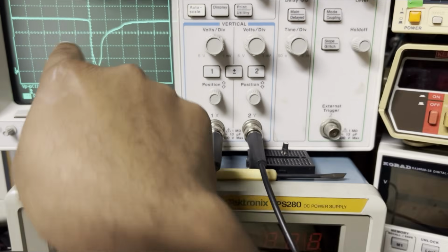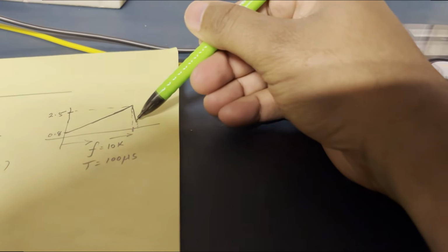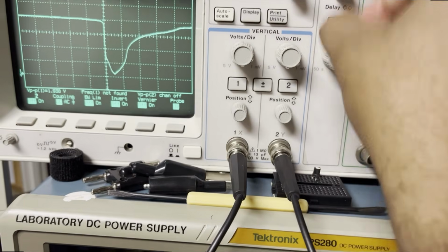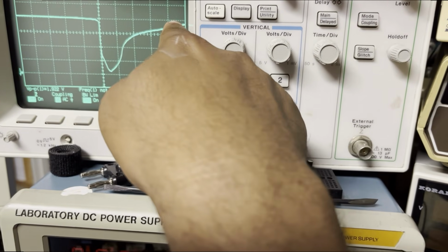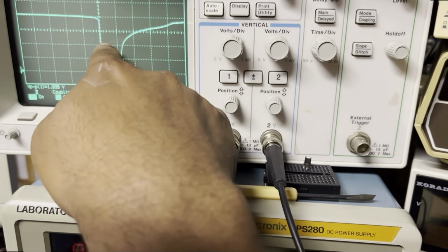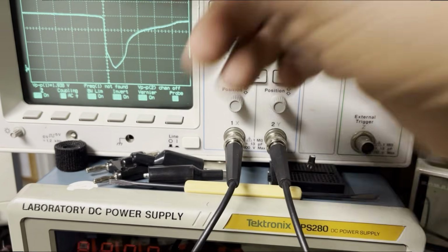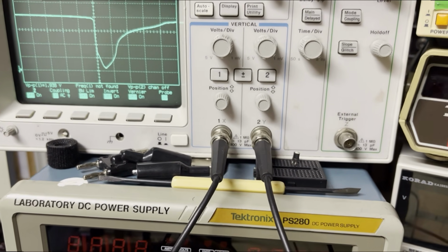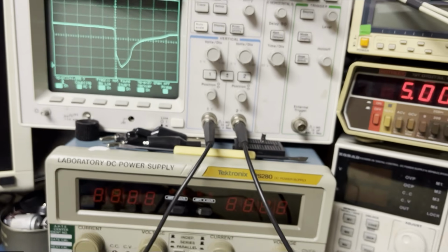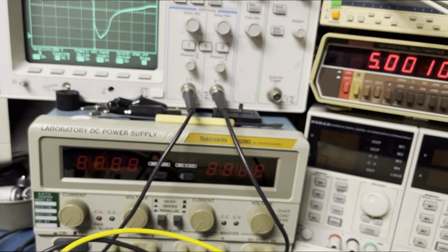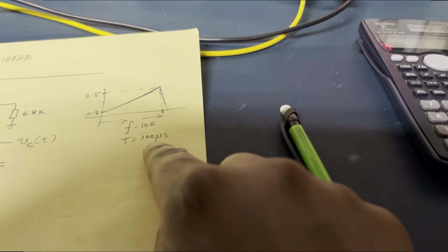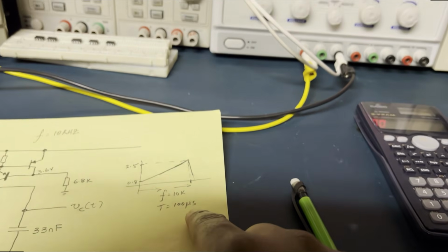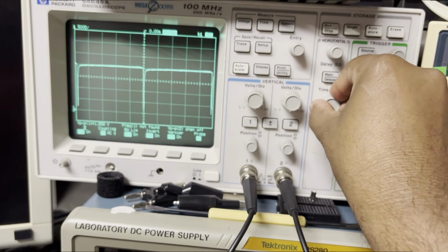There will be a slight time delay when we're doing our calculation. Remember I said we'll have a lot of error here that is going to contribute. If we measure it, from here to here is about 500 nanoseconds per division. 1, 2, 3, 4, 5. So about 2500 nanoseconds, about 2.5 microseconds, right? We have a 100 microsecond period, so the error is about 2.5%, so that's okay, right?